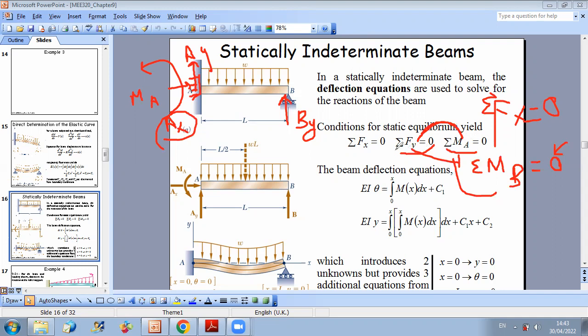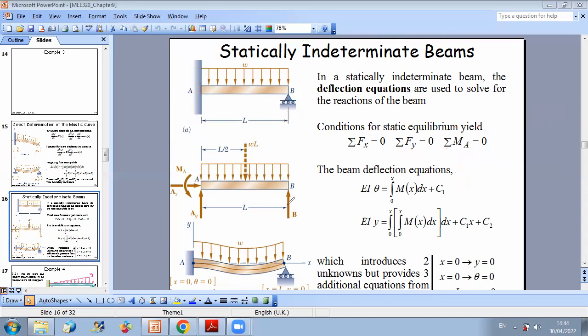Okay. So for these 2 equations, you have a freedom to select them. You can take sum of y equals 0 with 1 moment equation, or you can take 2 moment equations, and say, let me apply sum of moments about A equals 0 and sum of moments about B equals 0. Whatever combination you try, you will not be able to solve for the 3 unknowns, because in statics, in 2D equilibrium, you can solve for a maximum of 3 unknowns. So the challenge will be to go to another analysis to get a force equation. And now, since we defined in this course how we calculate deflection, the deflection concept will help us calculate our force reactions, in order to close the system of 4 unknowns.